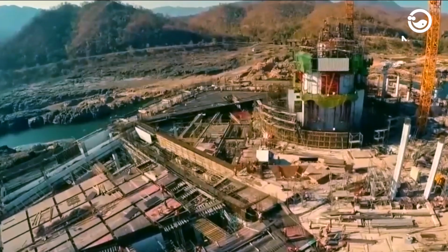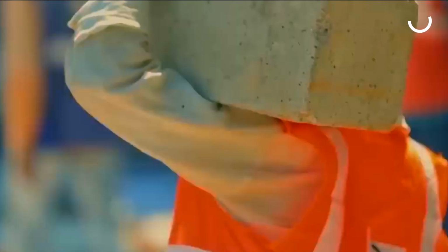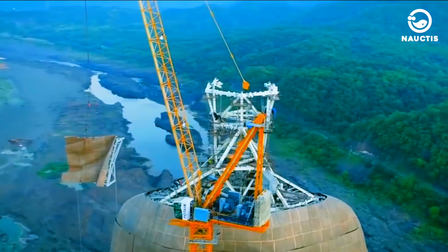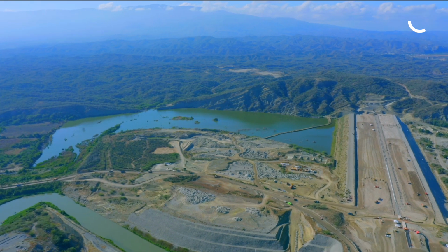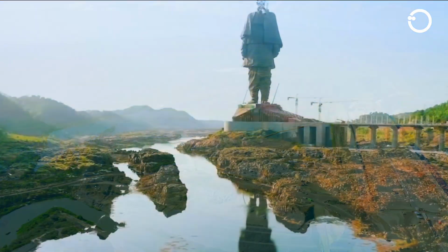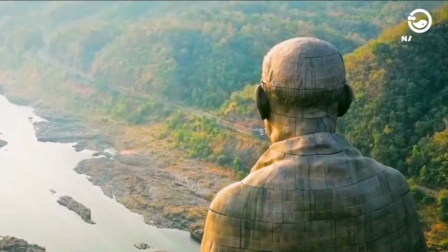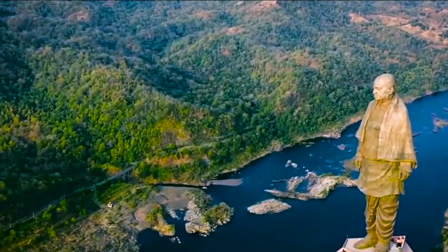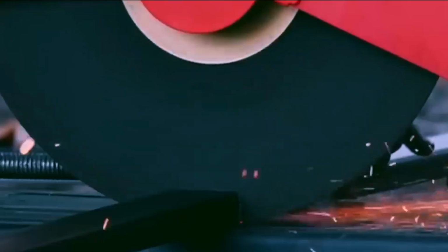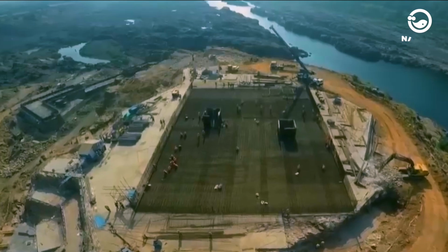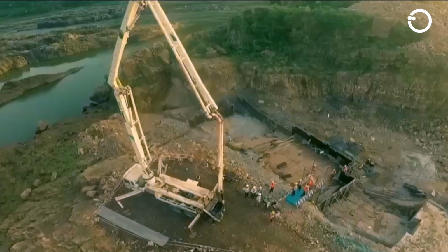Constructing the Unity statue was a complex and challenging task, involving thousands of workers and engineers. The construction process took about 4 years to complete, from 2014 to 2018. For access to the island, 2 ways are available. Mainly, a stone bridge was built at normal flood level, and then a Bailey bridge was built above high flood level. The Bailey bridge has 2 lanes, one for vehicle and material movement, and one for worker access. The statue has a composite core structure, consisting of 2 semi-elliptical reinforced concrete cores supporting the steel frame and bronze panels.